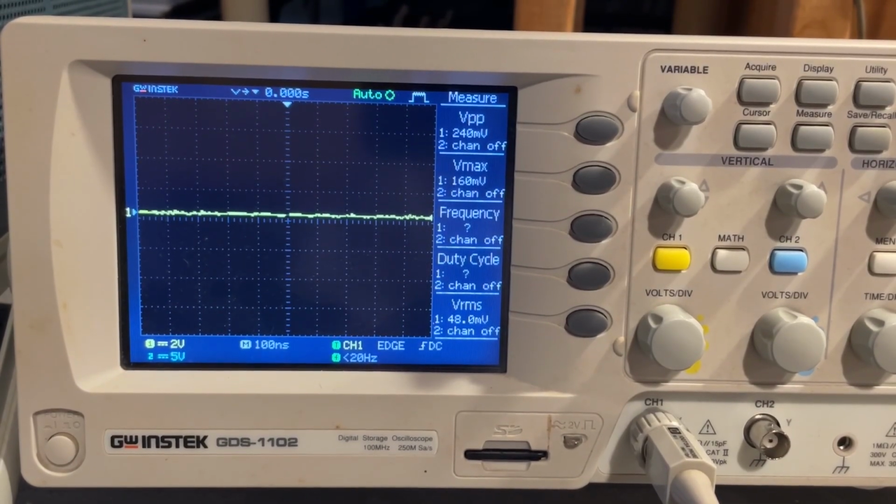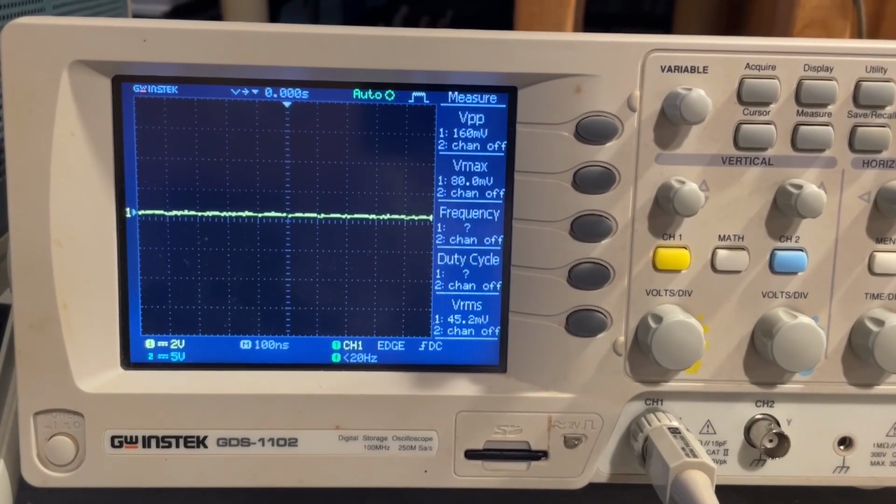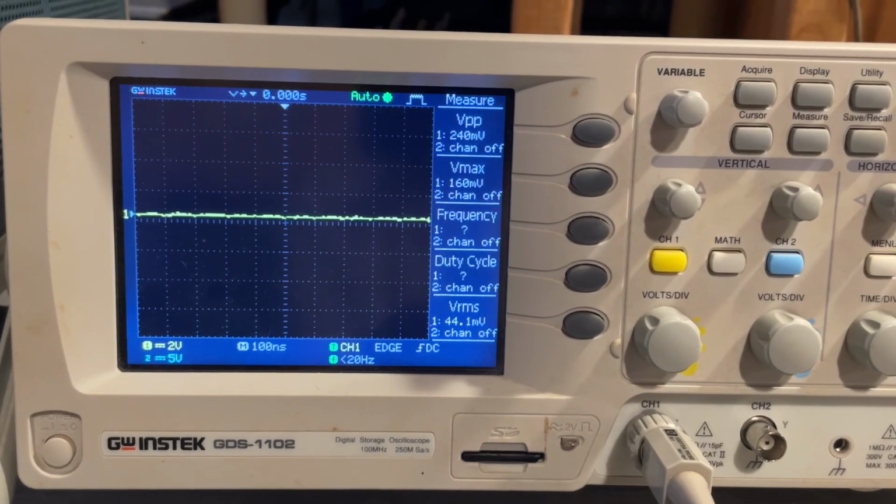And basically, we're stepping up 3 volts to 9 volts, so that's a 3-to-1 voltage gain. And then 3 squared equals 9, and 9 would therefore be the impedance ratio. So that's the demonstration. Those are the measurements. Next, we're going to be looking at the return loss of this type of transformer on the VNA, and then look at how it performs in an actual amplifier. So let me set that up, and I'll be back.